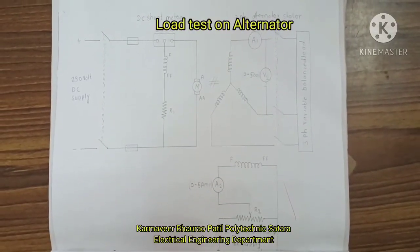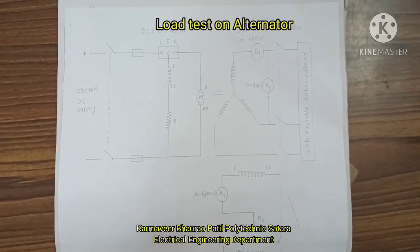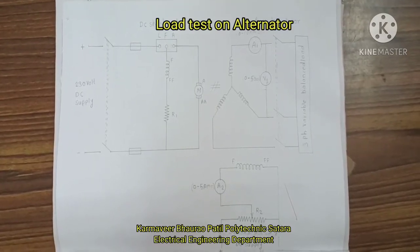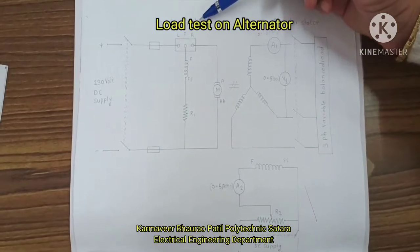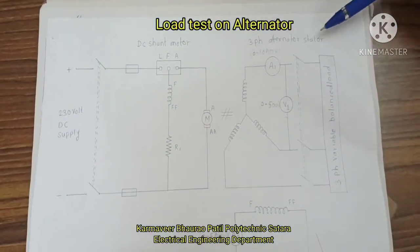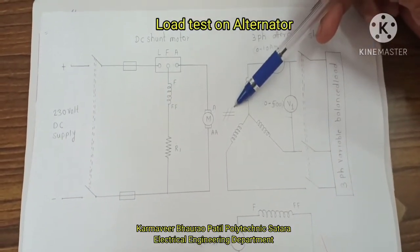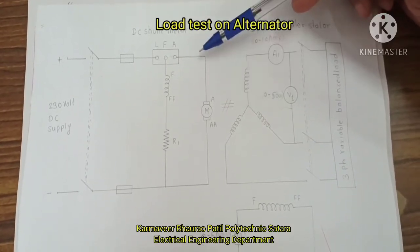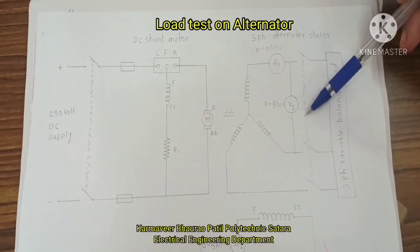The connections of this experiment are similar to the connections of the previous experiment, that is the open circuit test and the short circuit test of the alternator. So again we are using a motor as a prime mover, and with this prime mover we are starting this alternator. Alternator and motor are mechanically coupled to each other. So input mechanical power supplied by the motor will be converted into electrical energy.